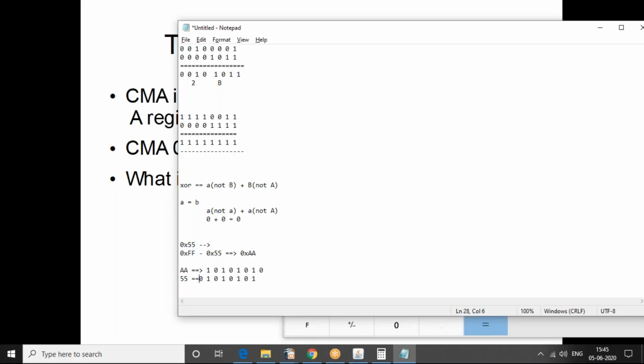Remember, all the numbers which I write are mostly hexadecimal, so I don't mark them hexadecimal explicitly, but for convenience, I can mark that as well. One good thing about the patterns AA and 55 is that they have an alternating 1 and 0. So this is a very interesting number to send out on any IOs. If you want to configure an IO and check whether it is working, if you make it 0 or 1, you might always have a doubt whether it is working properly, probably whether you put the oscilloscope at the correct place.